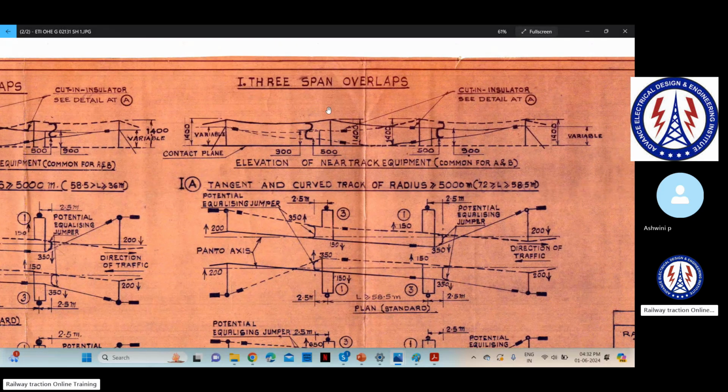See, I will have the isolator over here, and this will help me to separate the wire. What I will do, I will take a wire from here and put an isolator on that connection, and another wire will go over here and touch it. If I open it, I will make sure that this wire after this insulator is dead.